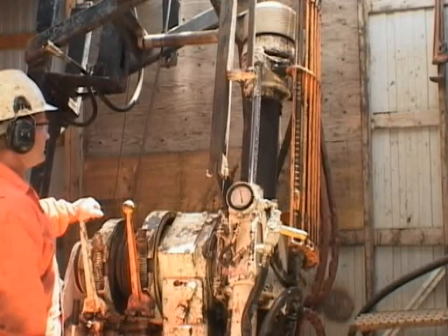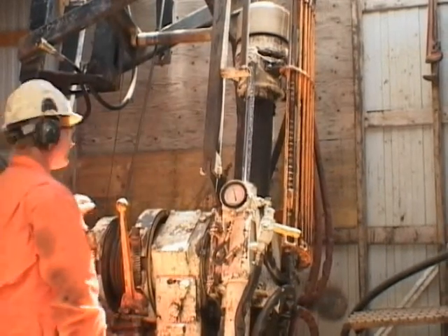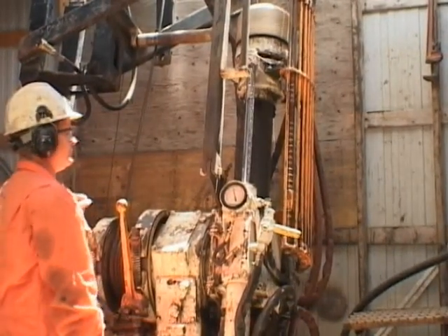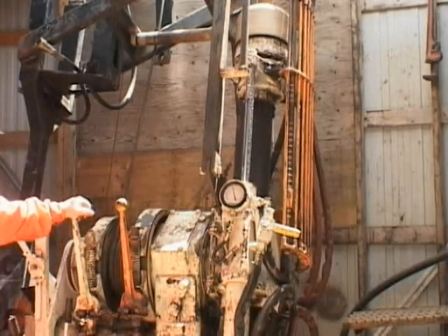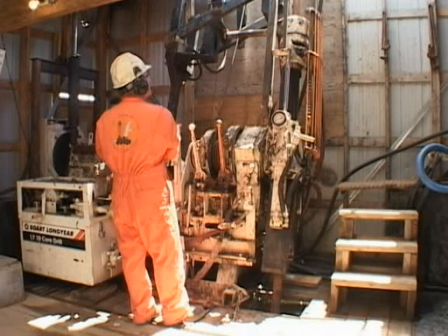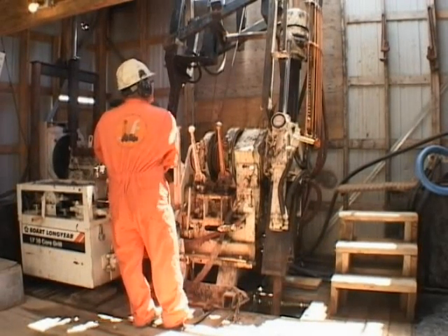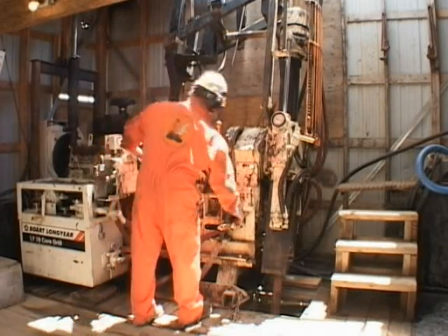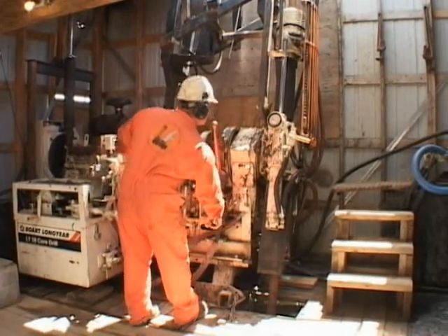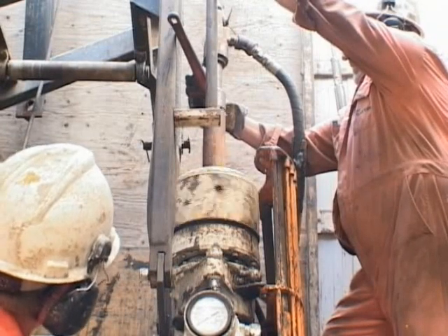The drilling process continues until the inner tube is filled. Shown here, the technicians are drilling in 2-foot increments, as represented by the stroke of the swivel head. This 2-foot stroke is repeated 5 times until 10 feet of core sample has been collected in the inner tube. However, some diamond drills are capable of a 5-foot, 10-foot, or even longer stroke. The inner tube is tripped out by removing the water swivel.